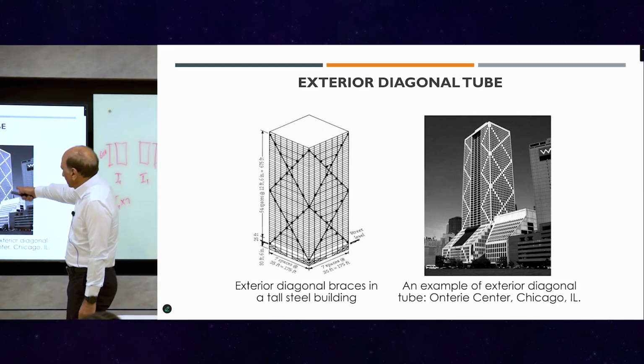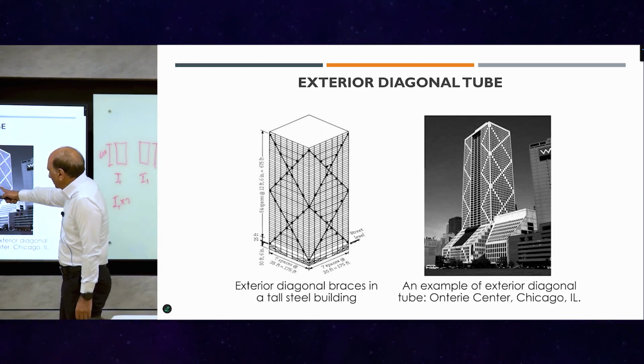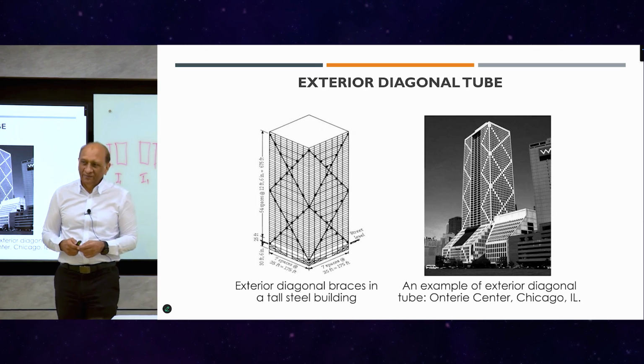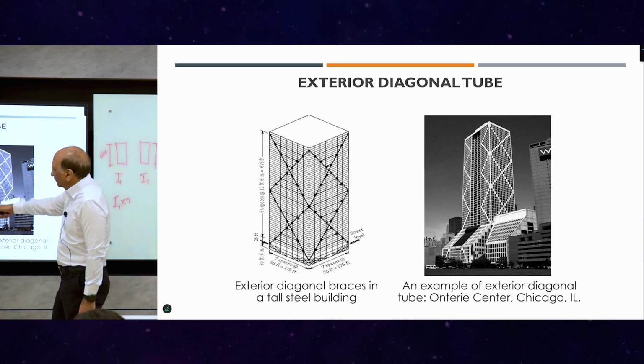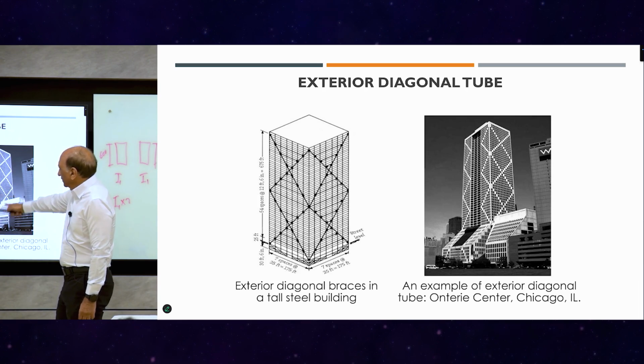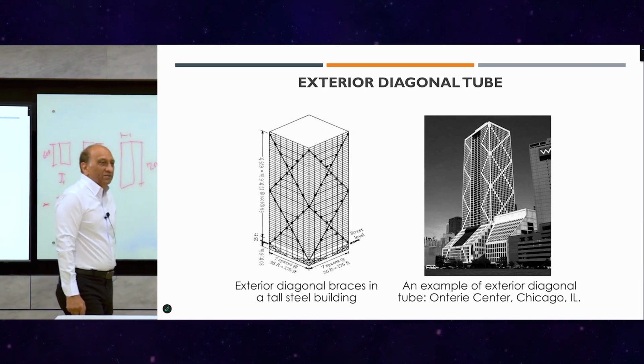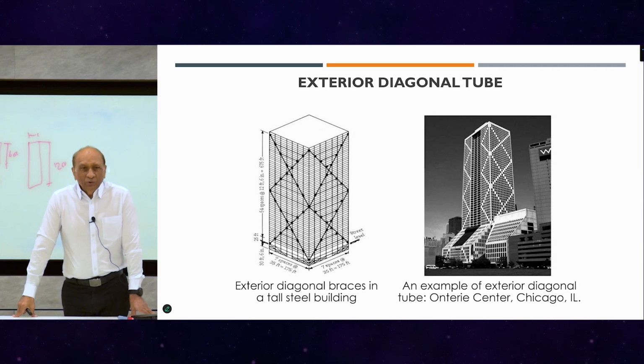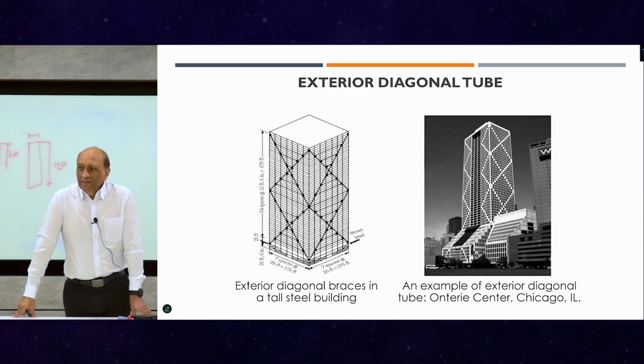So you see here, these tubes, and sometimes the tube is made by simply making some of the panels concrete walls, similar to the building that we did. So it's a very nice, beautiful building, but it's a tube system, diagonally braced to minimize the shear lag effect. So you can see here, engineers have been very innovative in taking the system and modifying it slightly wherever they noticed a problem to come up with a better system.